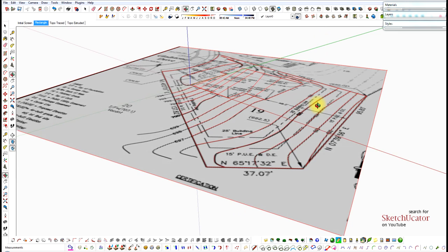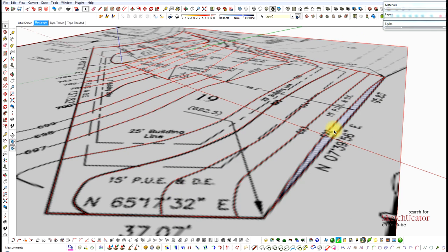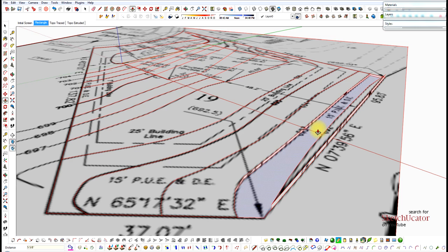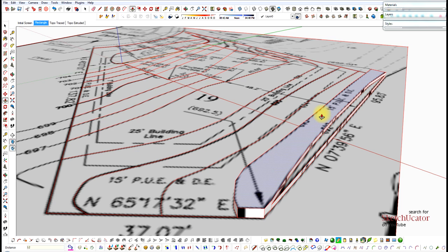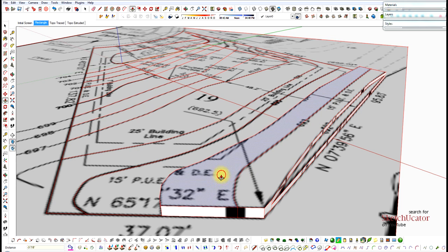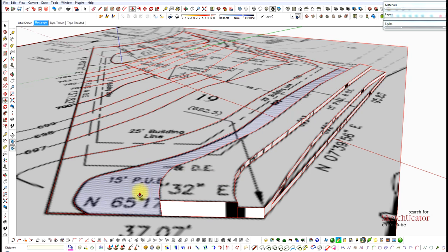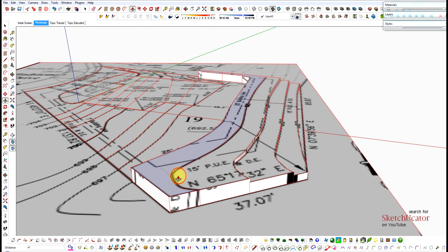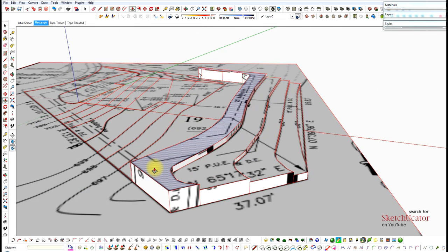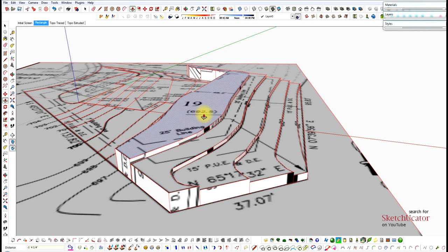In order to get this topography to work, we're going to take these chunks and just move them up. This is a 12-inch increment on this topography. Now I'll bring the first one up 12 inches. The second one I'll pull up and I'll inference or reference that first one and then add 12 inches to it. So you can do this in SketchUp anytime you're doing similar push-pulls and you want them to match. You just reference the one that you want it to match, and it makes things go a lot faster.